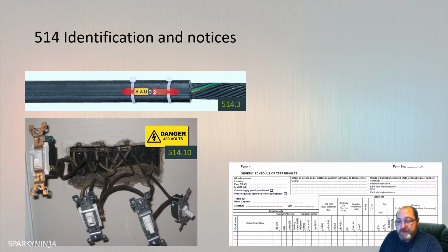Conductors by letters or numbers. The lettering or numbering system applies to the identification of individual conductors and of conductors in a group. So it must be clearly legible and durable. Durable meaning it needs to last for the life of the installation. It will be strong in contrast to the colour of the cable.